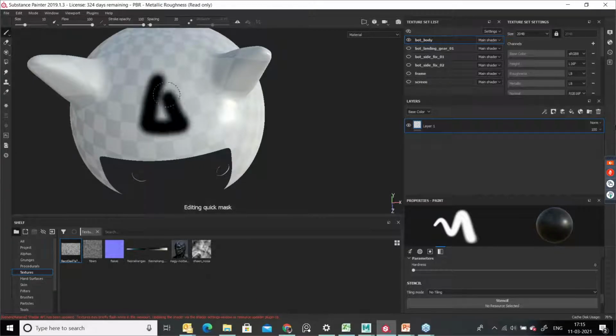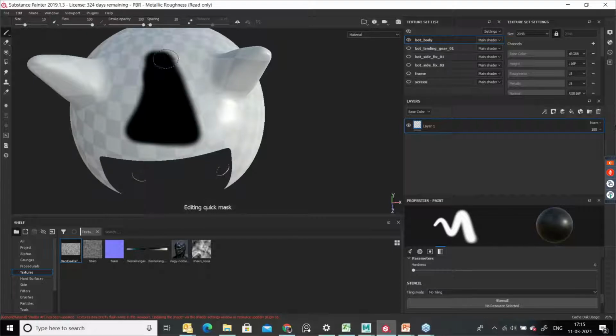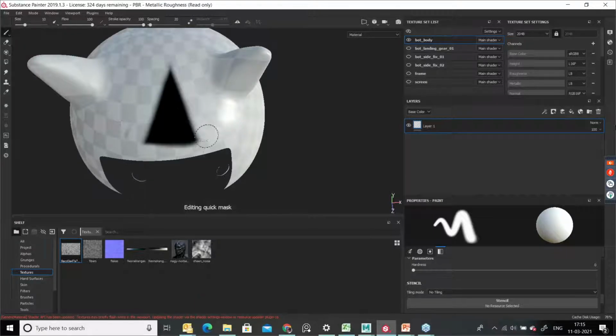This black color won't allow you to apply any stroke over here. See, this is a masked area. So in this area, it won't allow you to apply any texture. Y is the shortcut key for quick masking. Suppose you want to do some texturing process. Suppose you want to edit this, then you can just press X. X will replace and remove this black portion. Like this you can remove. So this area I don't want to apply any texture, apart from other area I want to apply some texture.